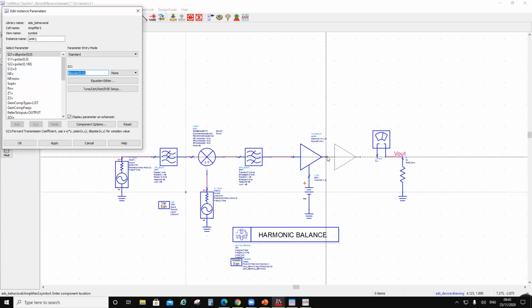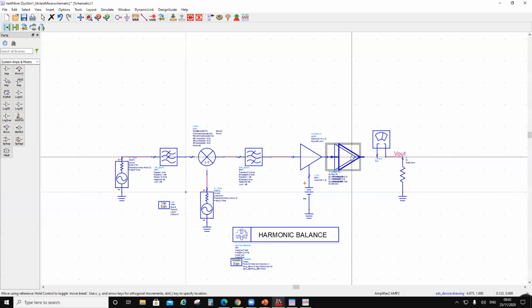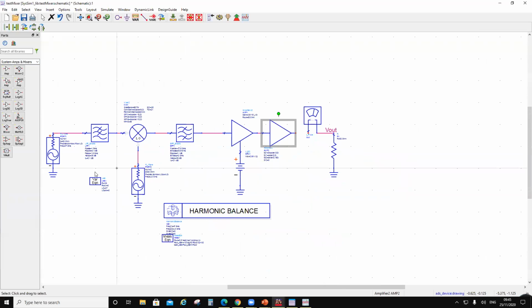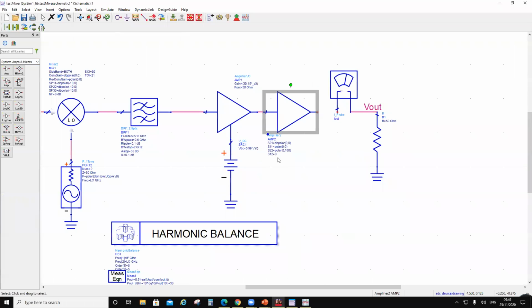Now, if I give an amplifier gain of, so what is the overall gain? 25. Okay. Let's say I want a gain of around 60, right? So there should be a 30 dB gain coming here on the PA. But then if you see, this is compressing at 25, so 30 more would be 55, right? So it will be compressing around there.